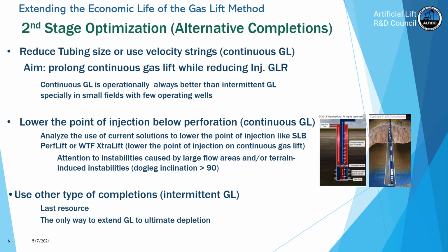There are places where, for some reason, the packer cannot be installed as deep as possible, or maybe the perforated interval is very long. In those cases, it's a good idea to check if using, for example, the completion proposed by Schlumberger, which is called PerfLift, or by Weatherford, which is called ExtraLift, could lower the point of injection.